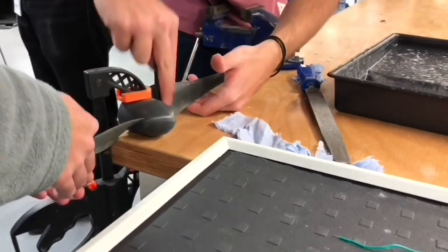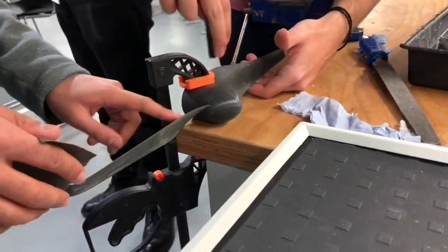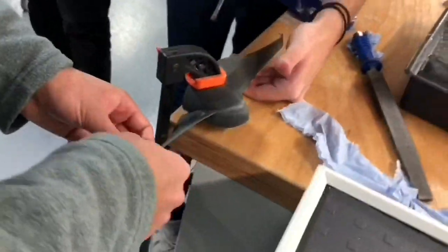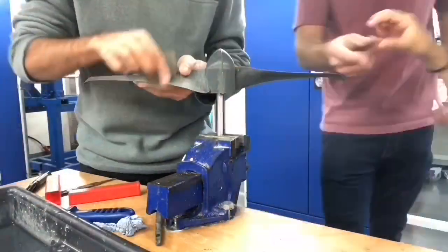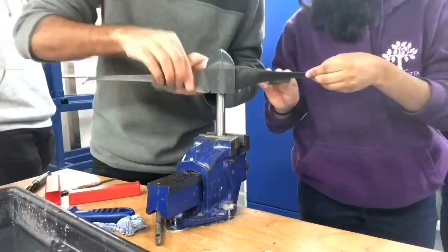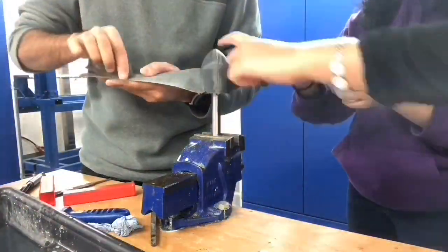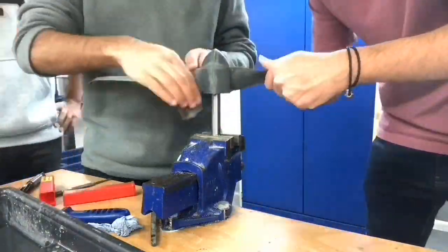We then sanded the part down to even out the surface, especially the trailing edge, which came out very rough due to the limited definition of the rapid prototyping machine. A combination of wet and dry sanding was used with successively higher grits. Dry sanding to even the surface and wet sanding to remove any scratches left by the dry sanding. This is important to ensure smooth airflow.